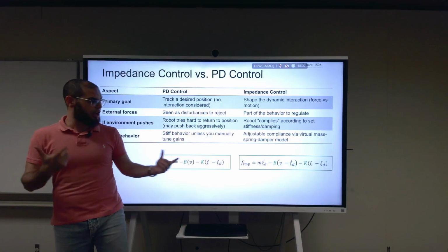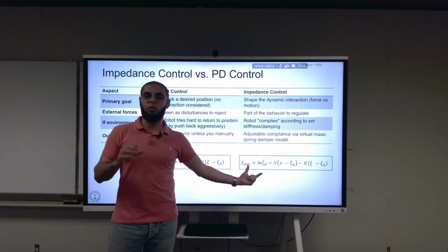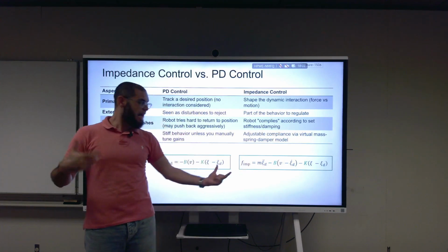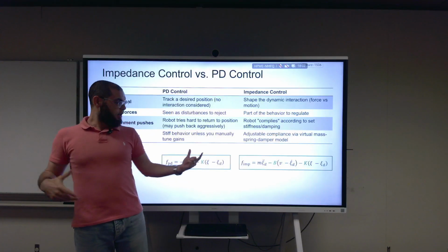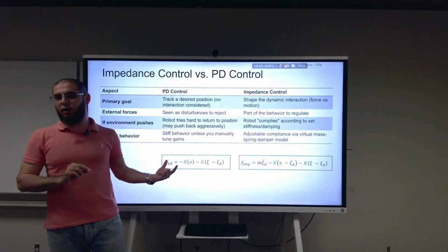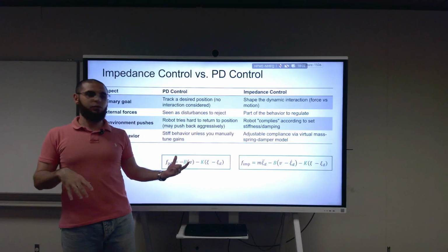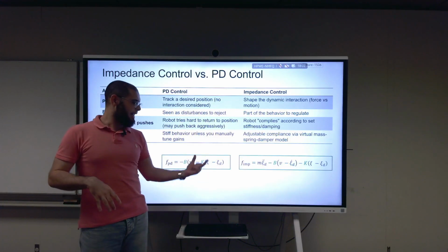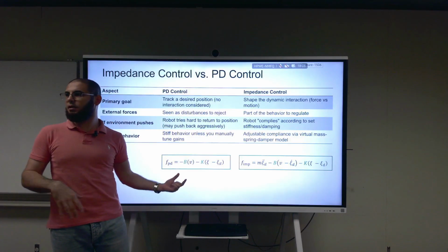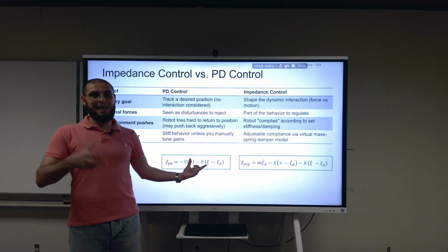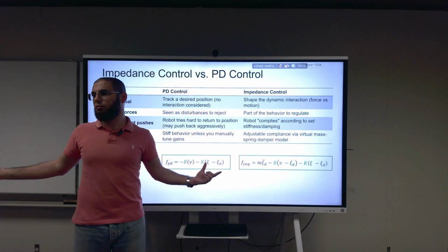Because he was not talking about the control law, and this is the main message I want to get out of here today. It doesn't matter what the control law looks like. It matters how you reach that control law. What is the idea behind how you design the controller? And we've actually seen that before throughout the course. You remember when we talked about PD control and energy balancing control? When we started with PD control, what did we start with? An error in position, an error in velocity, multiplied this by the Kp, multiplied this by the Kd, and then you get a controller. But was that way of thinking enough for us to go to geometric control on SO3?